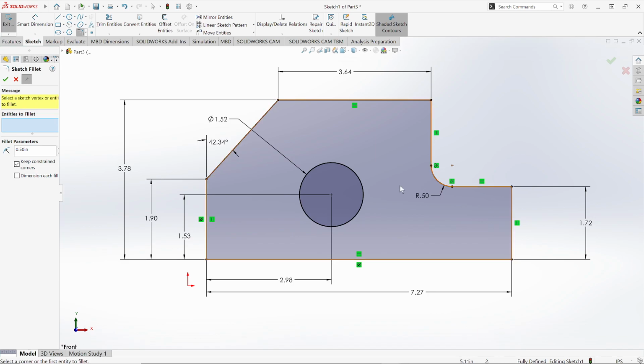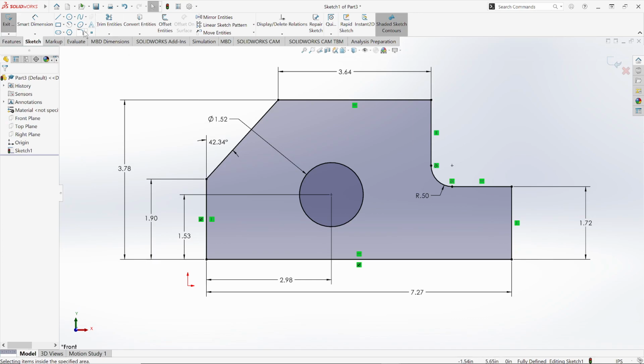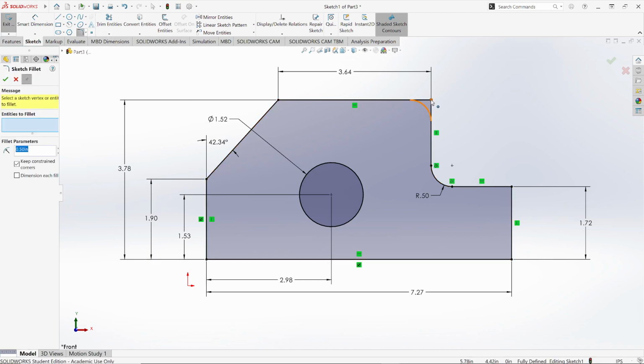Well, it's a sketch, I don't have to pull it off the drawing. If I did a corner on the top, this point here, and click to position, whoops. If I do corner and grab this point here, I feel like it's not doing it here. And then I hit this green check mark. I'm going to do 1/4 inch or 1/2 inch. Hit the green check. So now I got a 1/2 inch radius on the top.